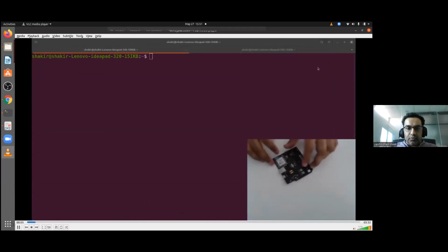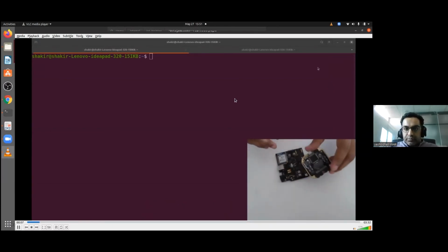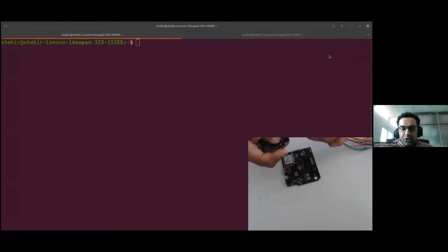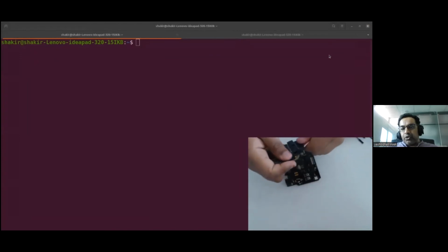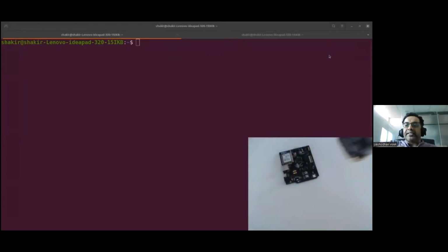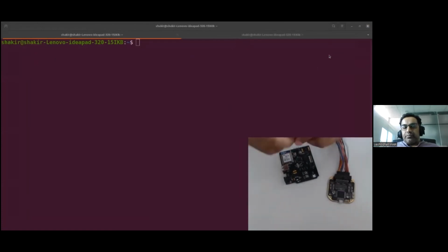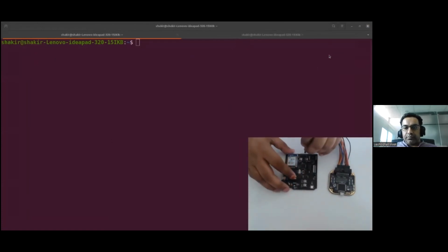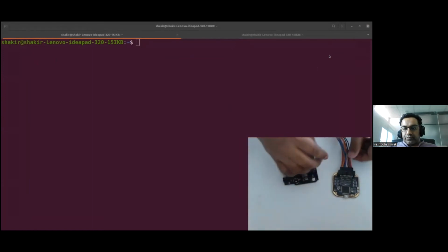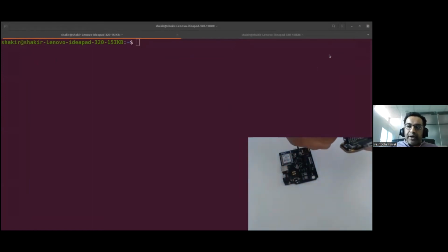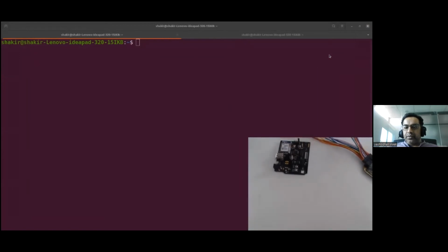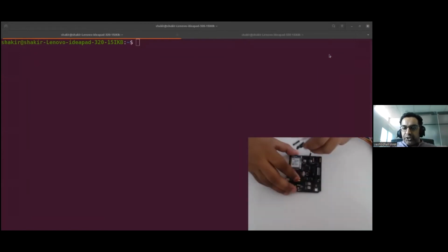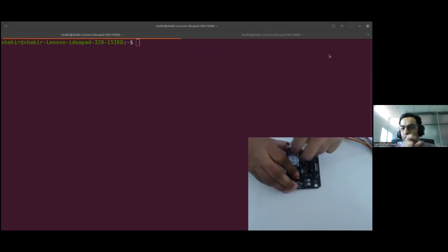So this is what we have. It is a similar setup, where you have a bus auditor, and now instead of JTAG, we are scanning for the SWD. First you connect the ground, and the remaining other pins associated with that. Again, you have those 8 header pins. As it's a whole header, we need to scan.